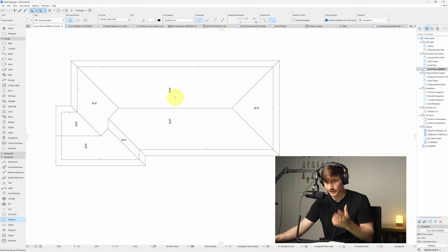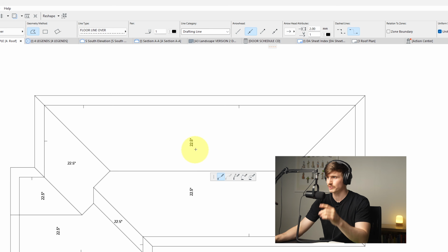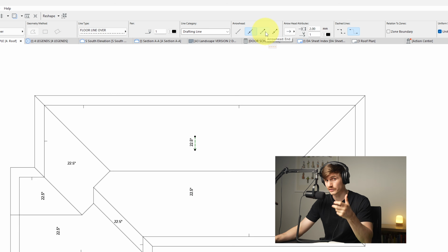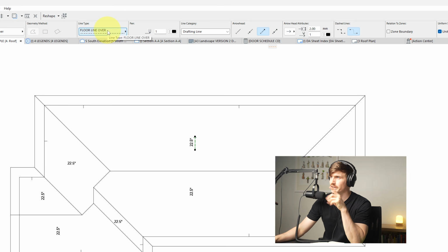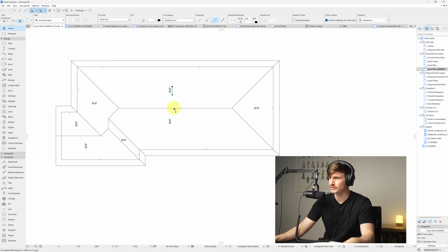We'll typically also use an arrow. So if we go to, say, the polyline tool, and just at the top where it says arrowhead, we'll click on one of the arrowheads. For the size, I've got number 2. And then if I click from this point, just down past the text here, and click once, double click, I've now got my arrow. It's currently set to the wrong orientation, so I'll click the other arrowhead end because we want it to point down away from the ridge. This is also a dashed line, so we're just going to change this to a solid line. So we can now use this one that we've set up and we can duplicate it around the rest of the drawing. And I typically like to line these up with our ridge line.